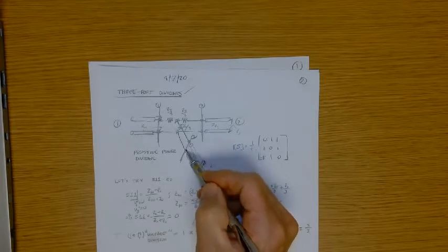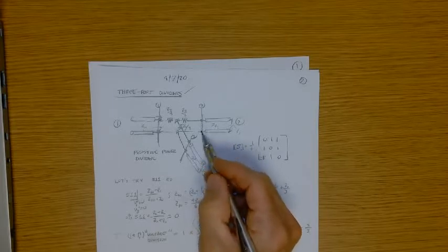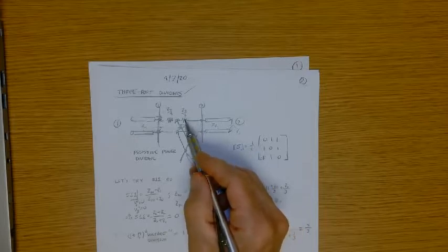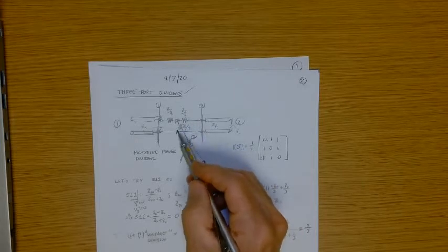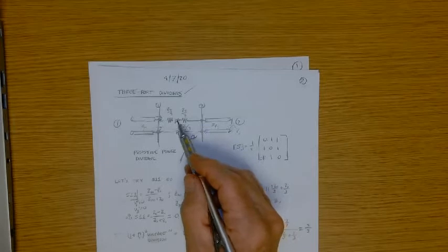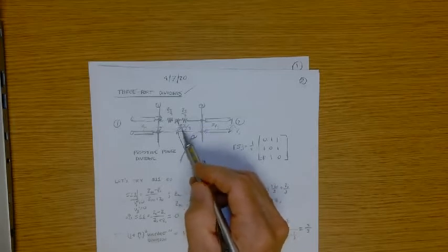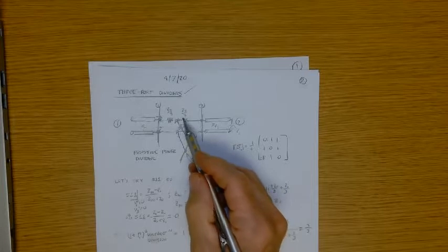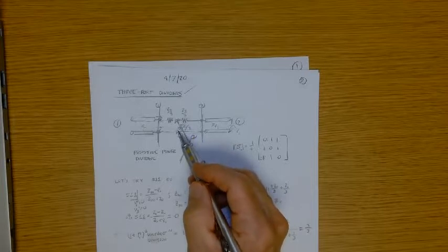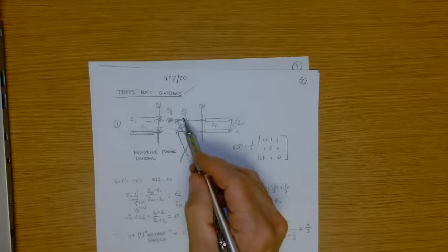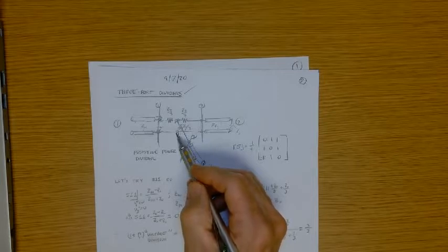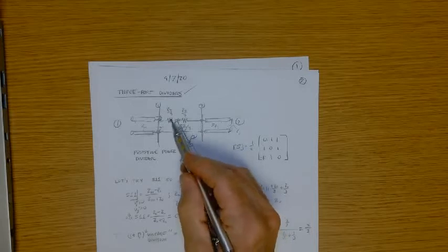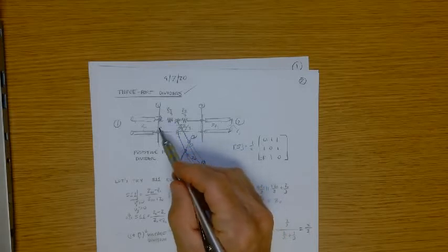And the impedance right here is Z naught, right? So I've got Z naught here plus Z naught over 3. That's 4 Z naught over 3 between here and here looking that way. 4 Z naught over 3 between here and here looking that way. And so we've got 4 Z naught over 3 in parallel with 4 Z naught over 3, which is 4 Z naught over 6, right? Equal parallel impedances split in the equivalent is half of one of them. And then I add that to Z naught over 3. That should be my Zn.